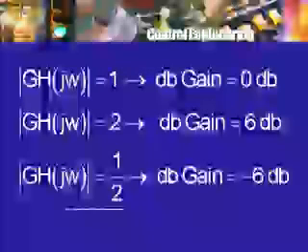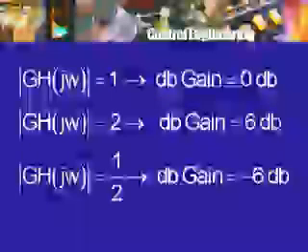What if the amplitude becomes 1/2? Then there will not be a gain, so it should really be called attenuation, but the gain will be minus 6 dB or the attenuation will be 6 dB, or halving, making something 1/2 is attenuating by 6 dB, or there is a gain loss, there is a loss of 6 dB, or the gain is minus 6 dB. Now as far as the gain is concerned, we do use this engineering approach of converting the product into a sum or a difference by taking logarithms.